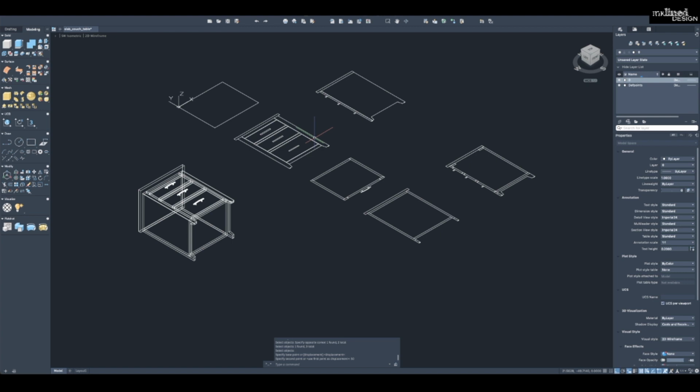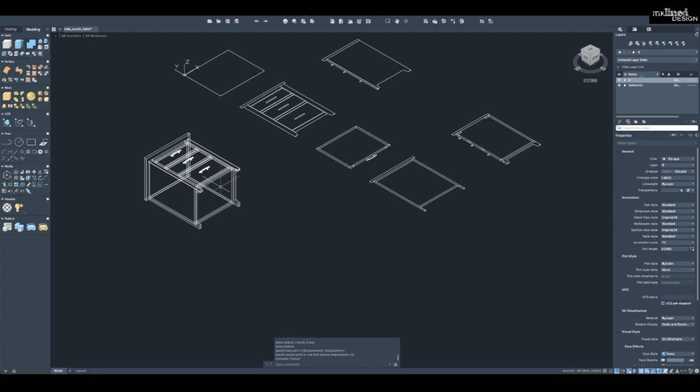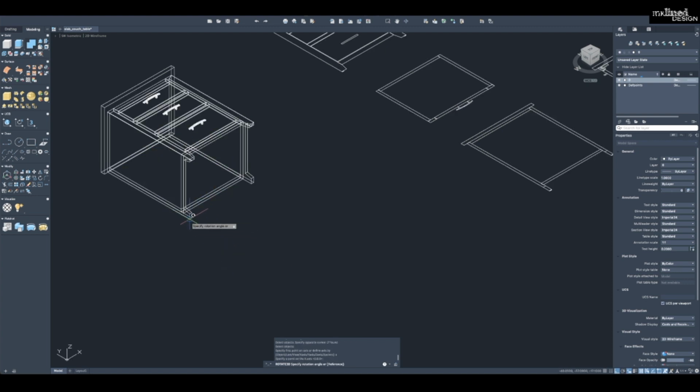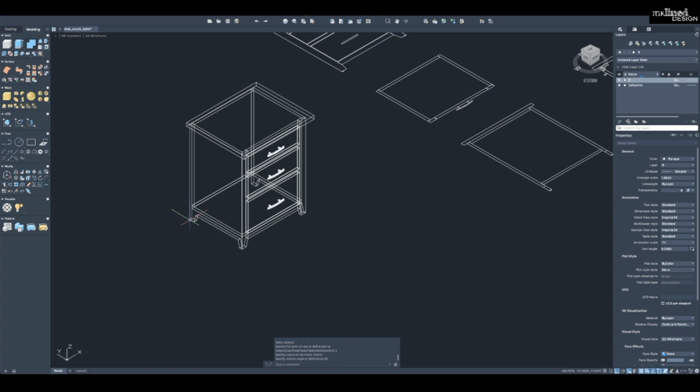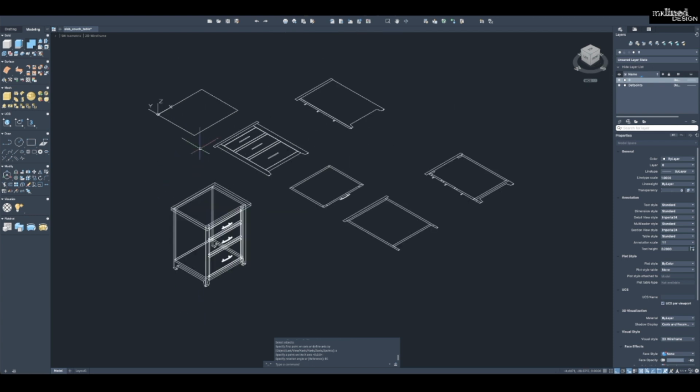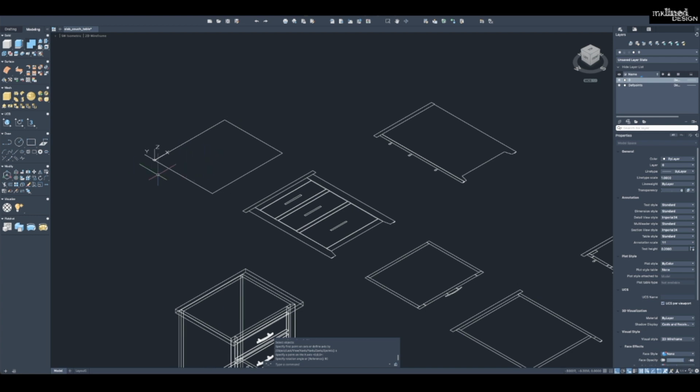So again, a couple different ways to draw things with solid objects and extrude. The next video we'll talk about booleans, these commands here, the union, the subtraction, the intersection, for making tapered legs and stuff like that. And then again, we can just rotate this object by selecting all, enter X, picking a leg, 90 degrees, have it rotate up. So one other thing that I sort of alluded to earlier is the top.